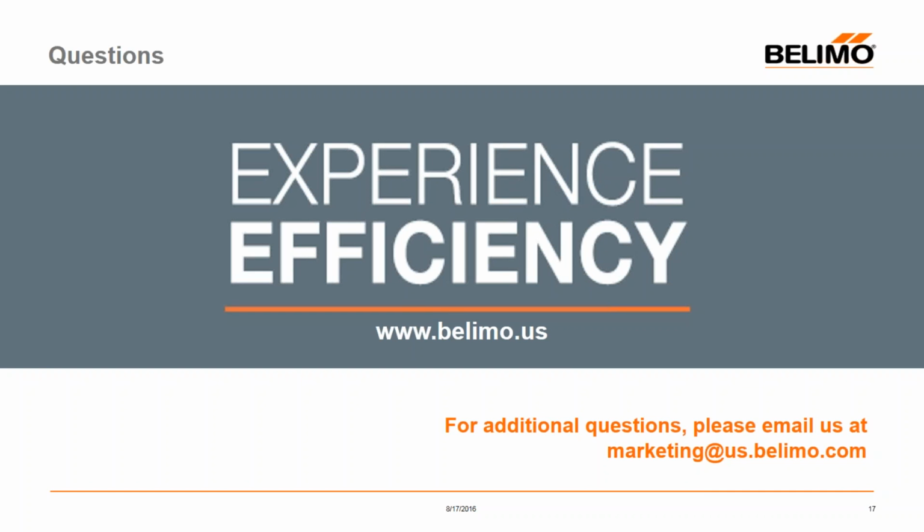If the IP address is changed in the field, will the tool automatically adapt to that change? No, it has to know it's a static IP, so you'd have to put the IP address into the network download or import screens.